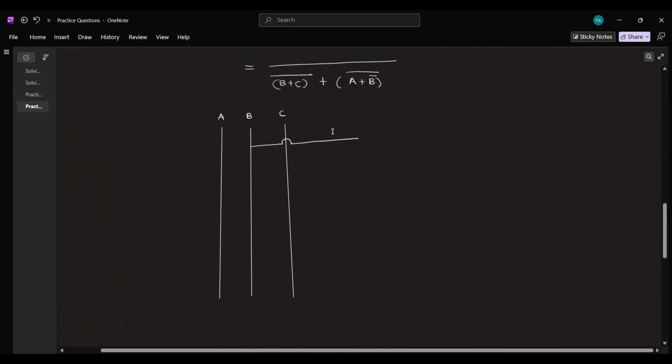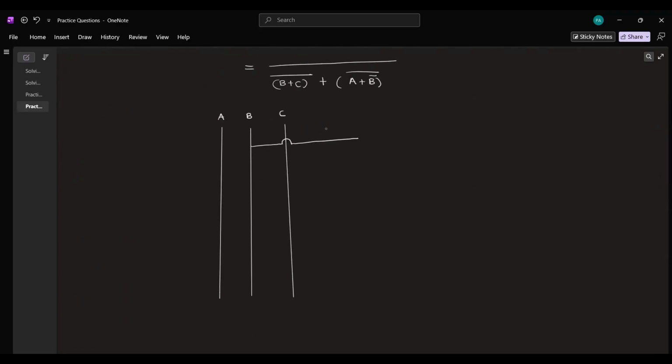But if you draw like this, you won't need dots, but this is not the standard nowadays. So that's why we avoid that. But let's do one question with that also. So we will send this through a NOR gate first. And then we have A plus B bar whole thing bar. So we need A and then B bar. For B bar, we know we have to send B twice through a NOR gate. It's very simple. Don't complicate this. This is very simple actually. Now we have to send these two through a NOR gate.